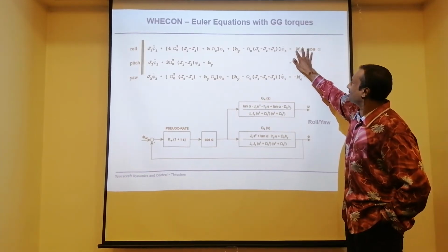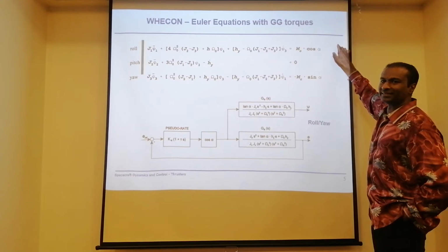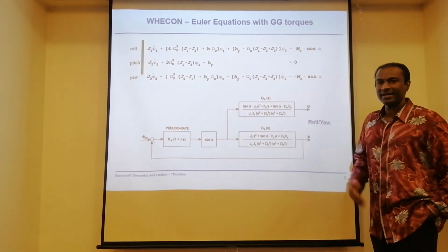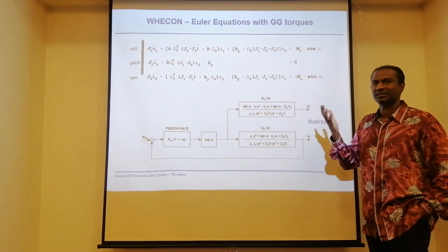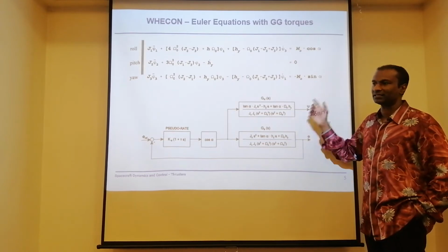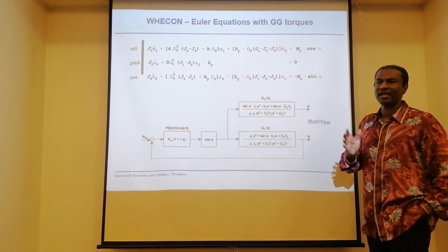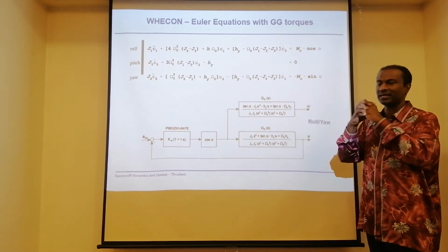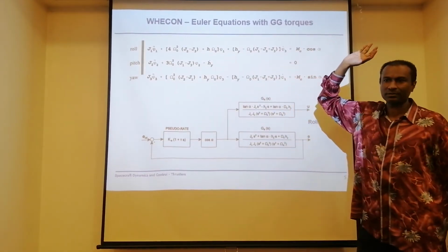Okay, let's say this is plus. There should be minus external disturbance torque. And let's say there is a minus 0.5 Newton meter external disturbance torque. I should give, that means the thruster should provide me plus 0.5 Newton meter torque. So both will be a net zero. When there is a net zero, nothing will disturb the set line. That's what it says. Okay?